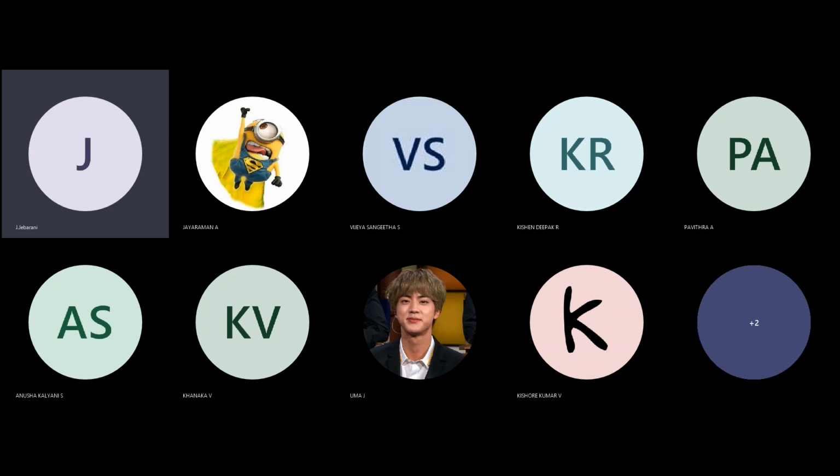It is a recent technology used to form hollow products. Majorly, the water assisted injection molding technique is the newest way to mold hollow or partly hollow parts. It is basically similar to the gas assist molding technique.